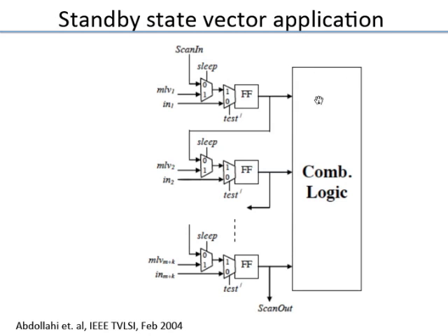When the chip comes back from fabrication, you can put in specific bit patterns here and test. Once you put in a particular bit pattern, you get a particular output bit pattern that you capture and serially scan out. Then you check, is this what I am supposed to get? There are a number of what are called test vectors which you put in. You see what outputs come, then you check. If everything matches, you are happy that the chip is okay.